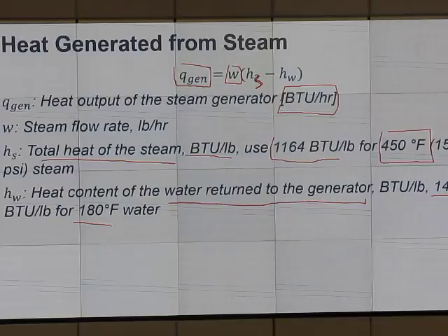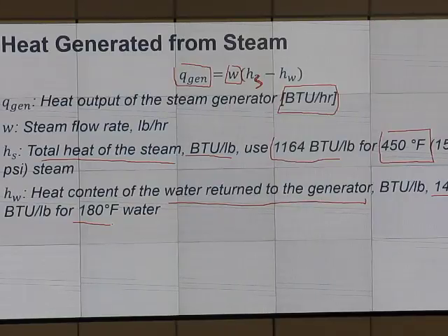So what happens is you have hot water at 180 F. You heat it to make it become steam. Put steam into a coil. The coil is inside the gun barrel. So this is used to heat the fluid in the gun barrel. After it goes through the gun barrel, it comes out. It will become colder, right? It becomes cool water. It's not cold. It's not steam, and it condenses from steam to hot water, and then you heat it again.